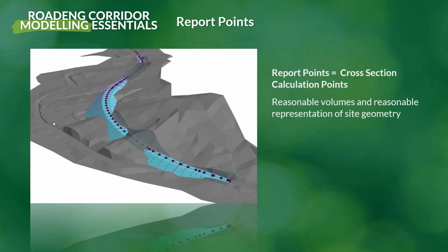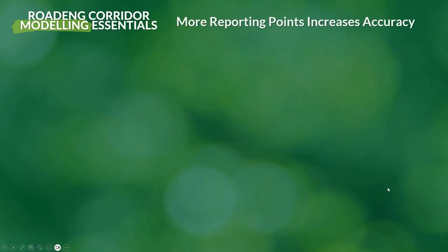There is one called an auto interval one, and that's the standard one that's going to be used throughout your project. And then additional report points get added when you implement curves, when you add culverts, and there's also another one that comes in when you explore a particular cross-section. That's your standard editable report point. You can also add those in manually. So there's a whole bunch of different classes of report points, but there's two major concepts worthy of going deeper on.